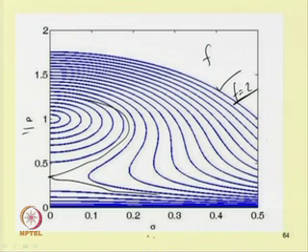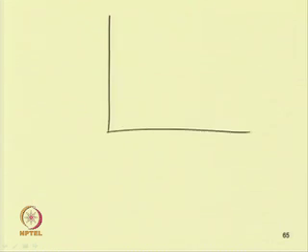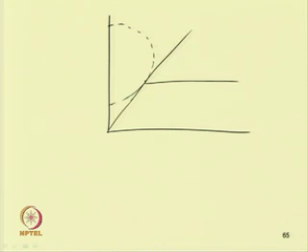So, in this way one can study the response of the system for self sustained oscillation and study the stability of the system. To study the stability of the system, one can actually plot the response and one can see that in this zone, this is rho versus sigma, one can have the saddle point. So, here one will have the saddle nodes.